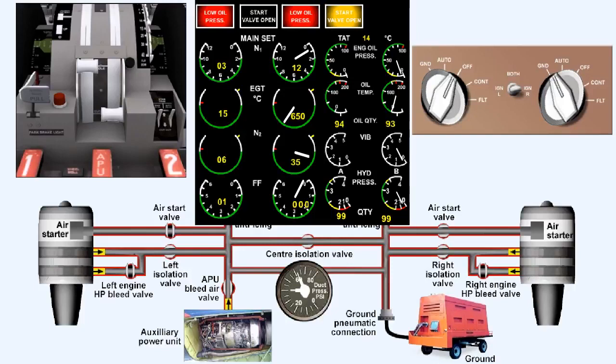Waiting for instructions or discussing the indications will almost certainly cost you or your company the price of a new engine. Hence the advice to keep your hand on the fuel supply control. If the EGT exceeds the limit by only 1 degree, the engine is to be considered unserviceable.